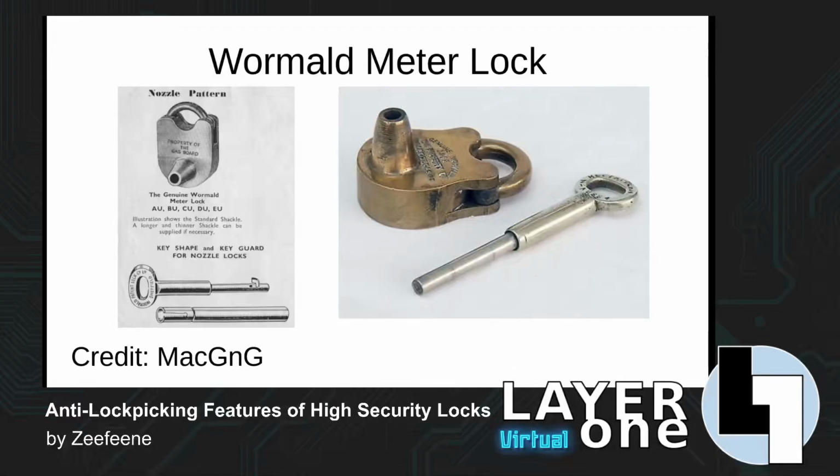However, from a picking perspective, if you don't have a tool with a moving end, then you run into quite a conundrum. You can either have a pick wire that is long enough to lift that lever into the correct height, but then it won't fit down that cylindrical channel, or you can have a pick that does fit down that cylindrical channel, but then it won't be long enough to set the lever at the bottom.